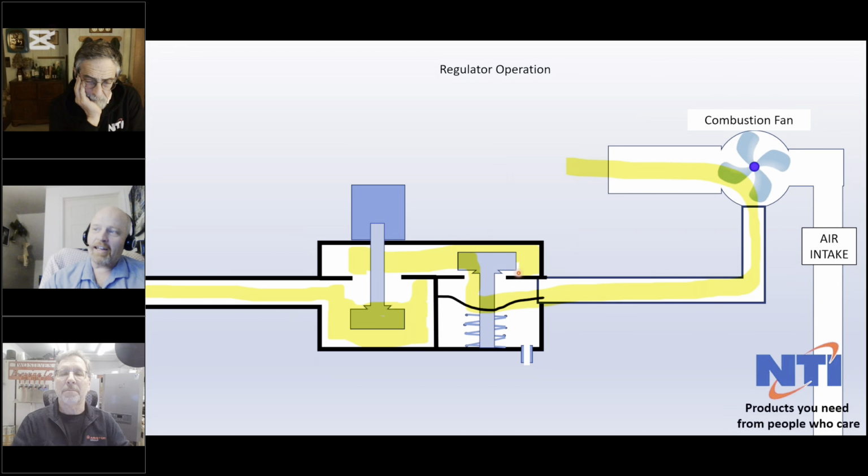So does that make it fairly critical that the cabinet is actually sealed? Oddly enough, no, because if the cabinet's not sealed, it effectively means you've got a larger air intake pipe. So it means the boiler has more available air, which means that you get more available gas. So the valve still balances out. So oddly enough, it probably means that it's less sensitive to problems than it would otherwise be.